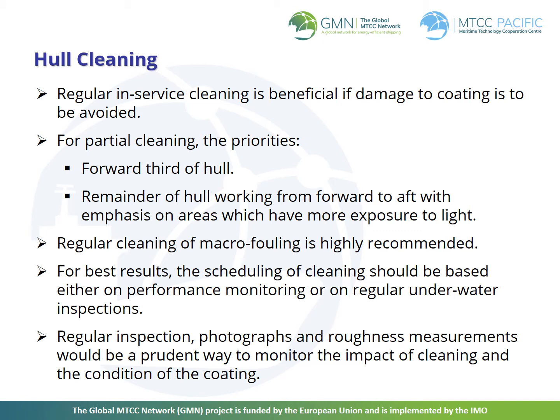Regular in-service cleaning is beneficial if damage to coating is to be avoided. For partial cleaning, the priorities are the forward third of the hull and the remainder of the hull, working from forward to aft with emphasis on those areas which have most exposure to the light. The regular cleaning of macro fouling is highly recommended. For best results, the scheduling of cleaning should be based either on performance monitoring or on regular underwater inspections.